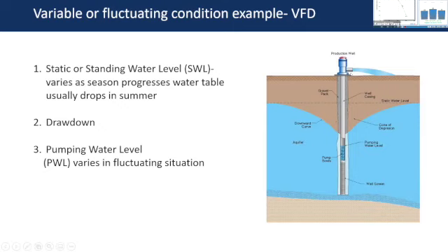If you go back to your pump curve, you get different flow rates out of there, which may mess up your irrigation system. If you only need a certain flow rate through the season, maybe you want to put, and the other thing that's happening now in California with the drought is these water levels are changing quickly and mostly going down, and farmers are having to pull their pumps out, put a bigger horsepower pump back in. So a lot of times it's cheaper to oversize the pump a little bit, put a VFD and run it slower. And I'll do a demonstration of that right now.